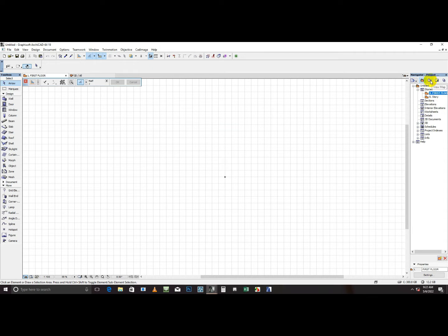Now if you come to these other buttons here, we have this View Map. Our project has not much, so it will not display so much information there. We have this Layout Book. This is where you save your work if you complete your working drawings and you want them for printing, you come open this.